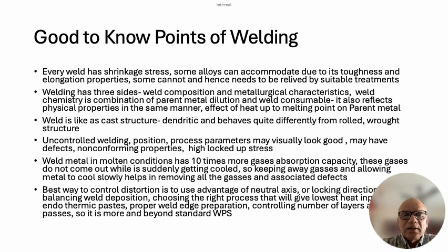Now, unless we give sufficient time for the weld to solidify, and ensure that during solidification these soluble gases, which are absorbed into the molten weld metal, are released, they will reflect as porosity or some kind of inclusions.